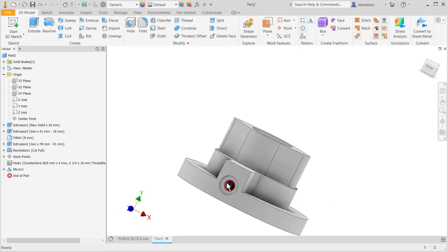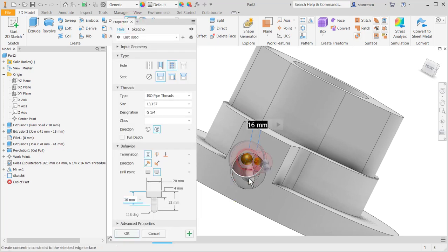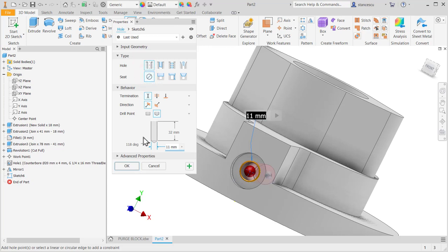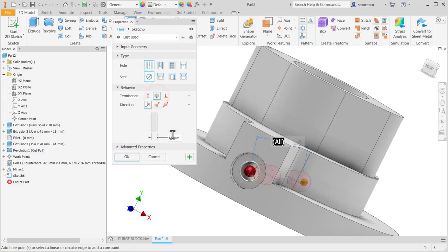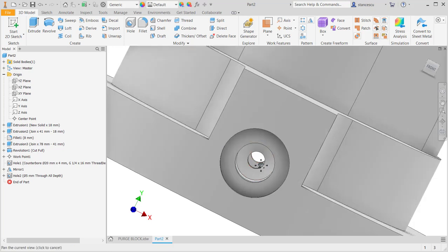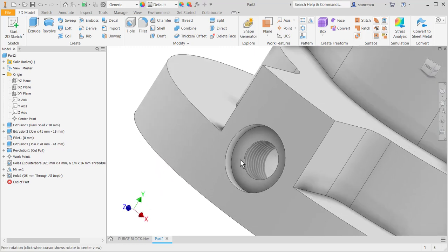This means that I select this face, no important, this face, concentricity, not threaded and without counterbore, all the way, diameter of 5. Okay, now you see there is a hole through. Very nice.